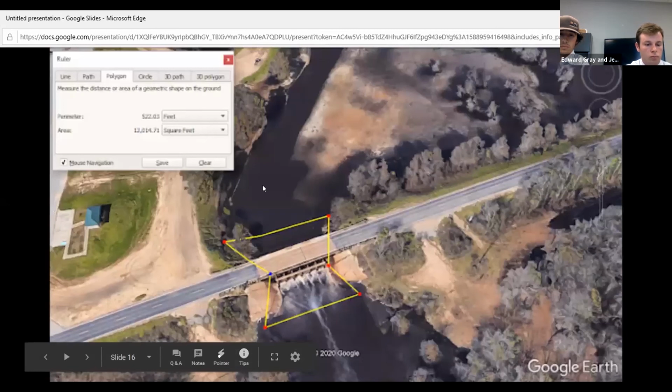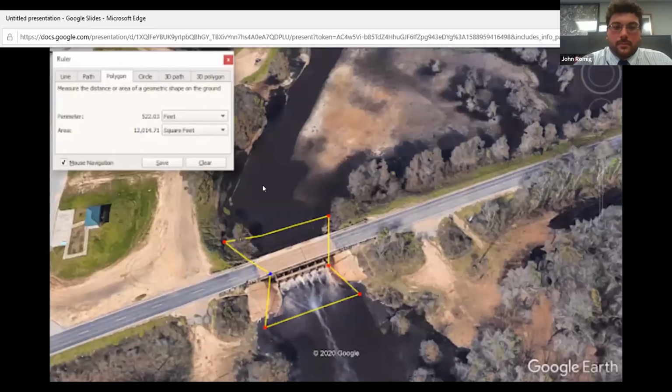So just throughout the process of working with the CE group and brainstorming, I remember our first site visit, as we went out there, we brainstormed and thought about ideas of what we would have to do. One of the key points was that we'd have to put sheet piles down to keep the water off of the construction area. A nice idea we came up with was putting the sheet piles down in the ground before we deconstruct the bridge, so we could drive the sheet piles off of the bridge.